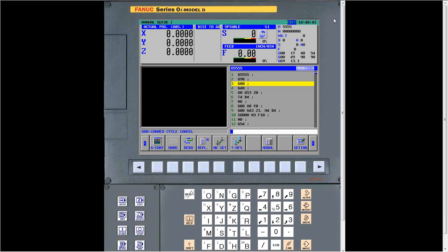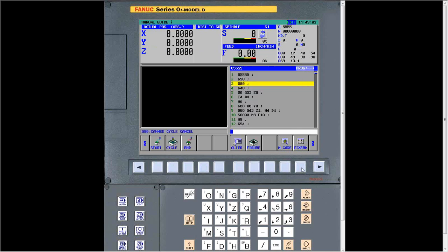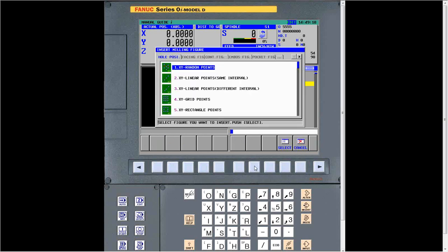How do you create a contour in the XY plane? Okay, that's very simple, and that's why I left this setup. When you go to do a contour cycle, whether it be an outside or an inside or something like that, once you fill out all those cut parameters, Mark, it will prompt you into this contour figure.